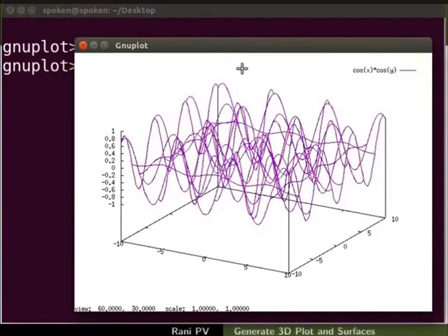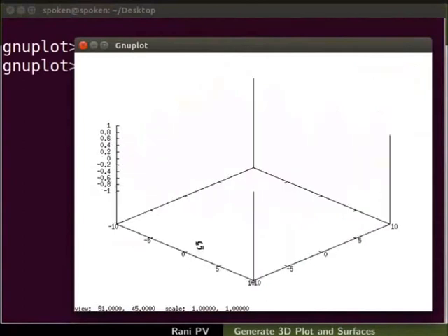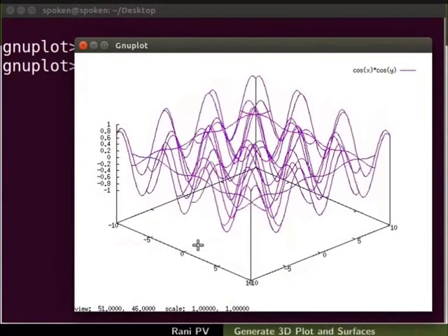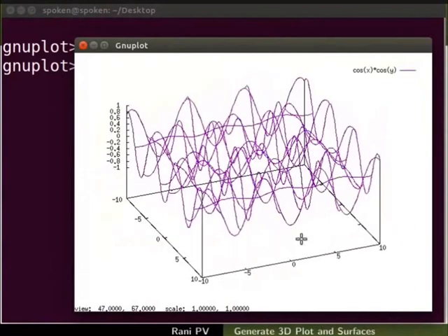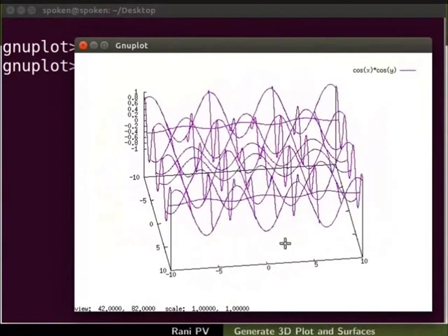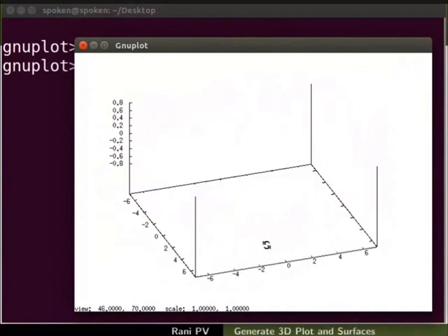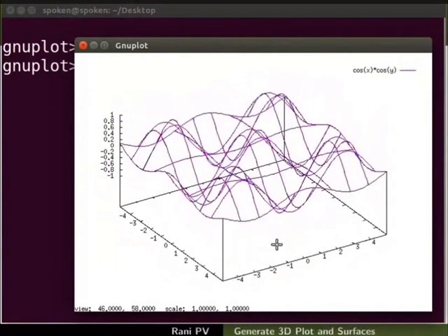The splot command generates 3D graph in the graphics window. Besides x and y, the third axis is the value of the function in the plot. Hold down the left mouse key. Move the mouse to rotate the graph and change the viewing angle. Zoom in slightly into the graph to see a wavy surface. Notice the surface is plotted in a wide mesh style.